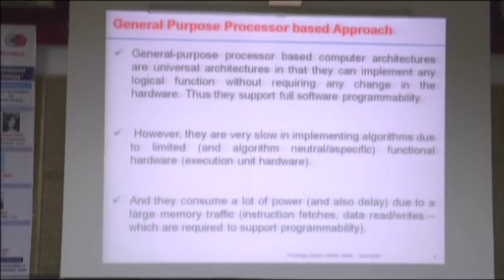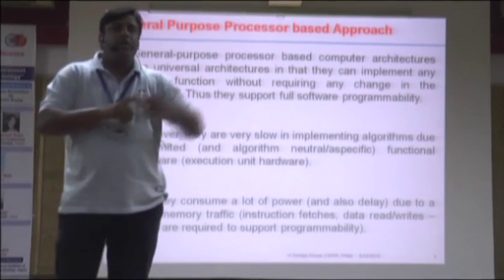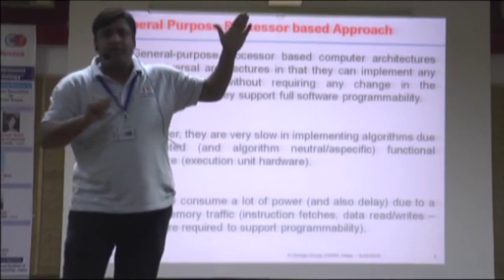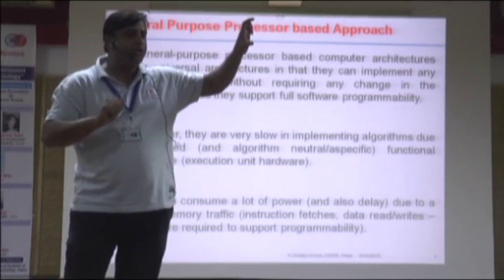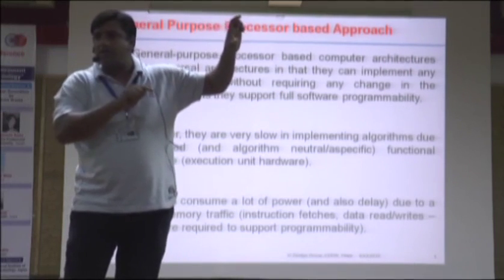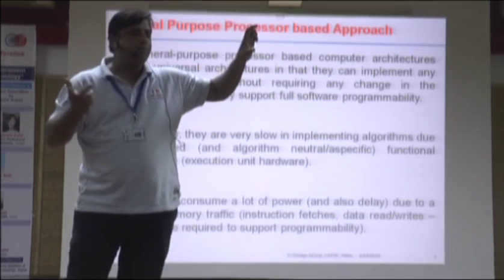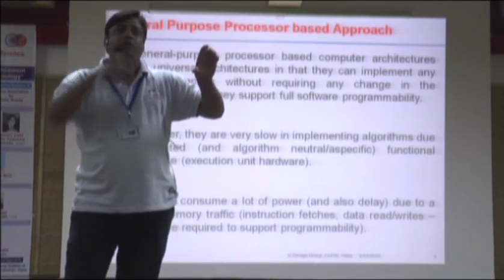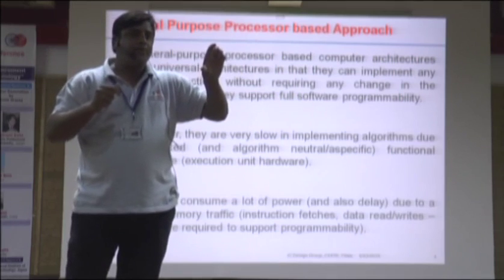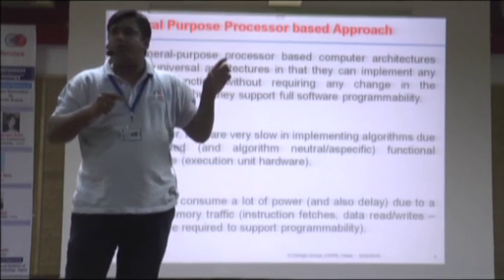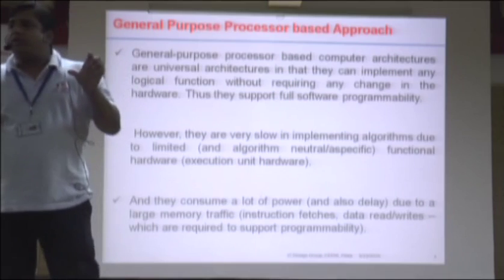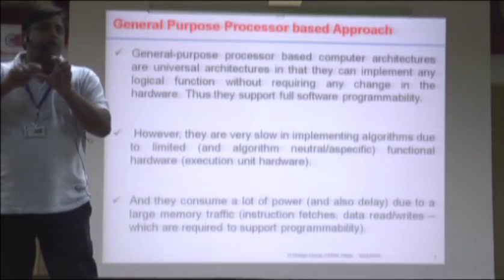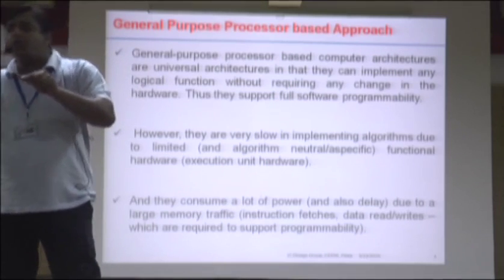तो सबसे पहले आपका प्रोग्राम मेमोरी में रहता है, ठीक है. So you have to fetch the instruction from the program memory. So you require one memory operation. Then you have to decode that instruction, what that instruction does. Then you have to fetch the operands from the data memory. So this is another memory operation. Then you have to execute, and then this generated result will be again stored back into the data memory.